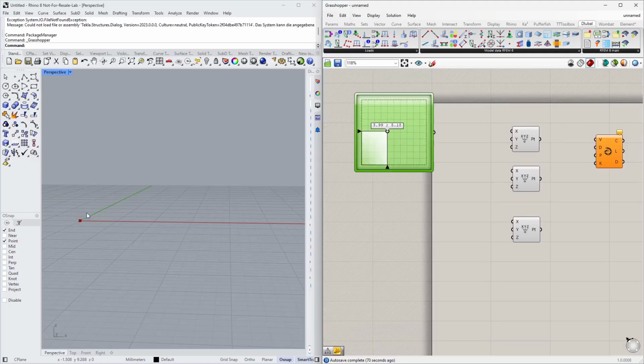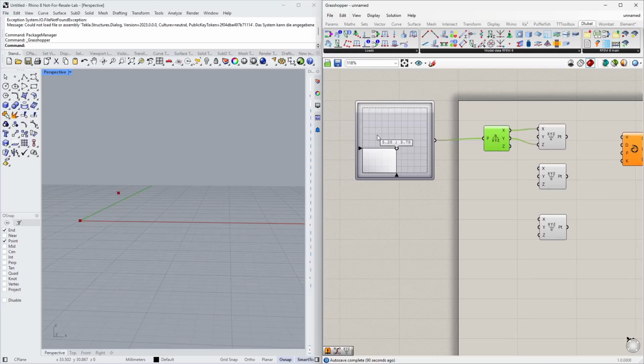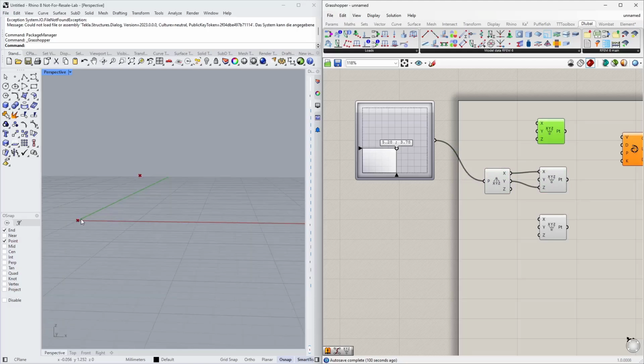Now my curve will be in the xz plane, therefore I need to deconstruct the node that I get here. So I deconstruct the node and I build it again, just using different coordinates. So x should remain as the x coordinate. The y coordinate, which I can modify here, should be the z coordinate. So you can see now, actually that's already the second node, my bad. The first node should be at 0, 0, 0. So that's the first node here in the center of origin.